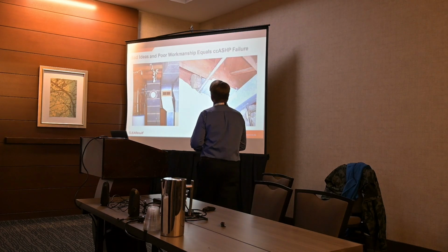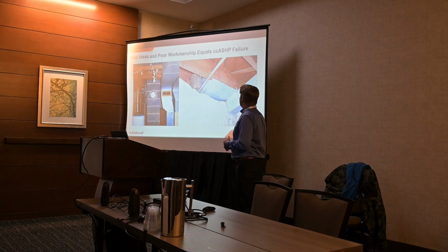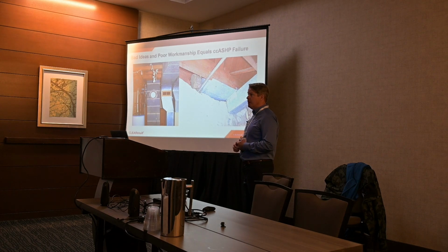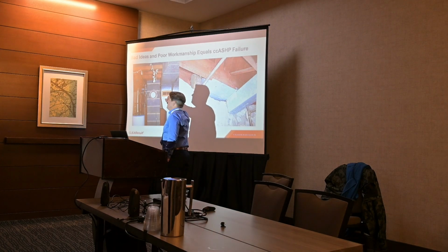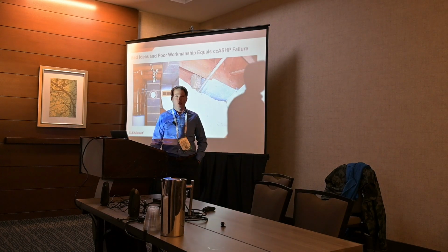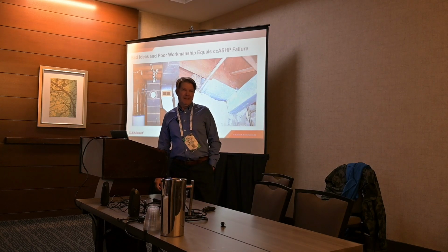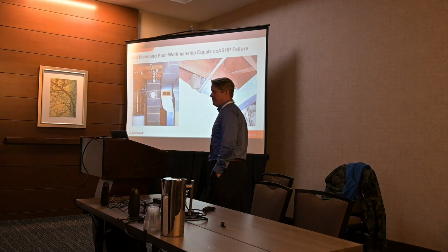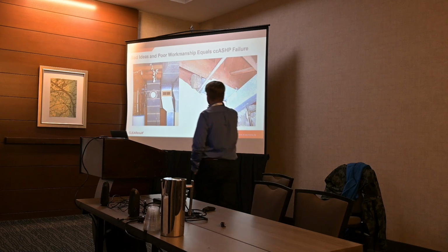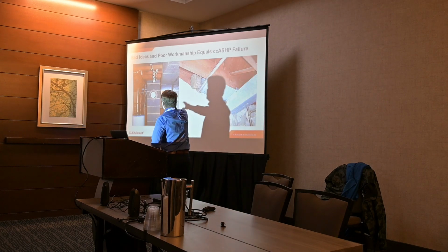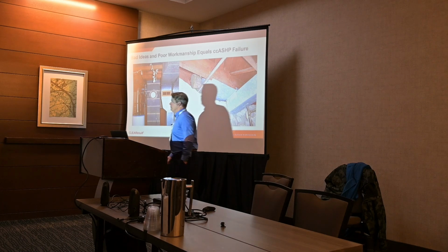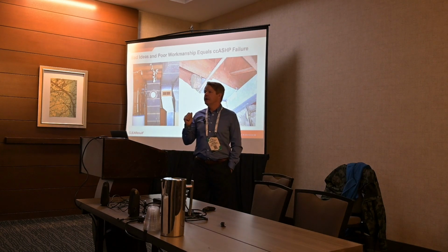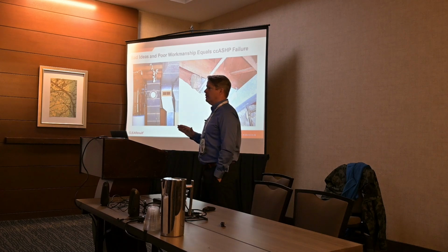Okay, so bad ideas and poor workmanship equals cold climate air source heat pump failure, okay? What is that? That is an unfinished basement with a return in it, in an old home. They probably added this because they didn't have enough airflow through the system, and so doing that gave them more return flow, which improved the flow through the system. Good idea to improve the flow, bad idea to take return air from unconditioned space ever, right?